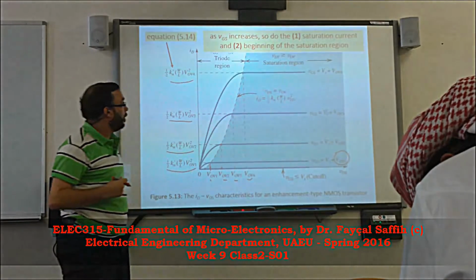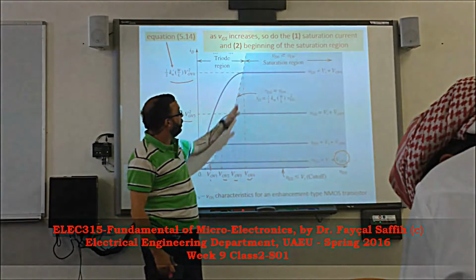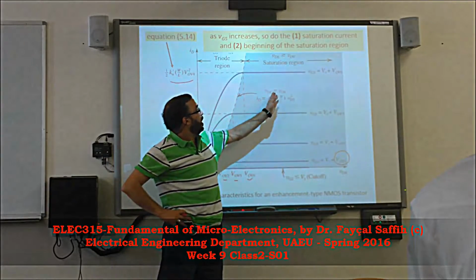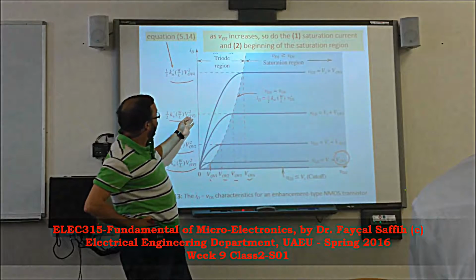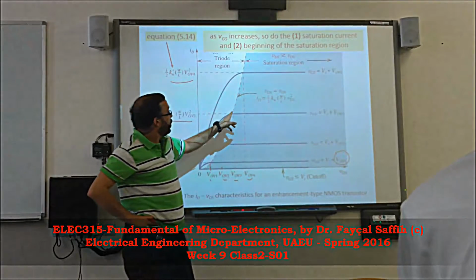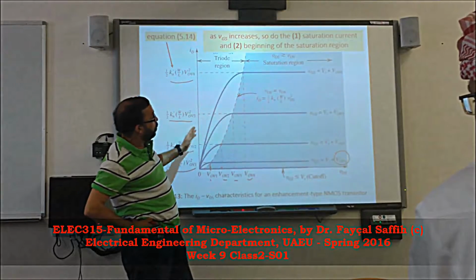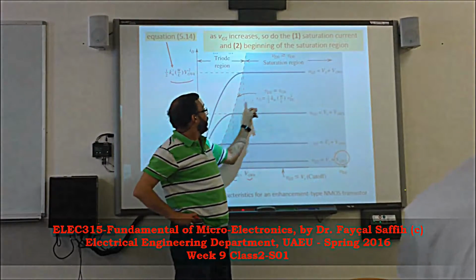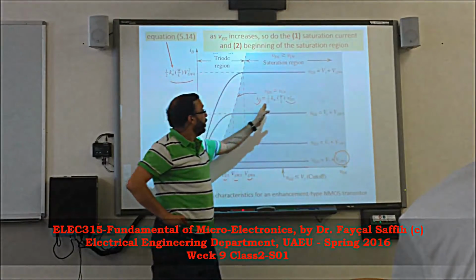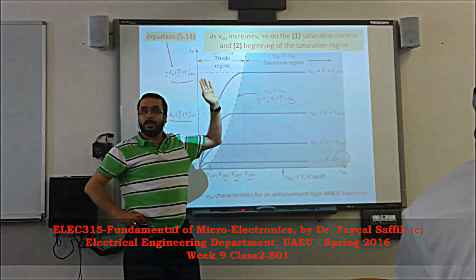There's nothing really simpler than this, I guess. If you want to know, for example, what the curve of the boundary is, it is basically this. You are replacing in the equation, VDS only. This is the boundary, which is this equation, because the boundary satisfies both the saturation equation as well as the triode equation, and they reach the same equation. So you can see that on the boundary, the dotted one, ID is dependent on VDS squared. When you plot this curve, you're plotting this function. That's it.